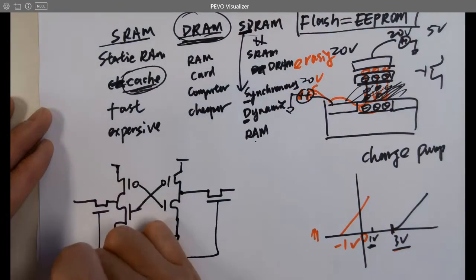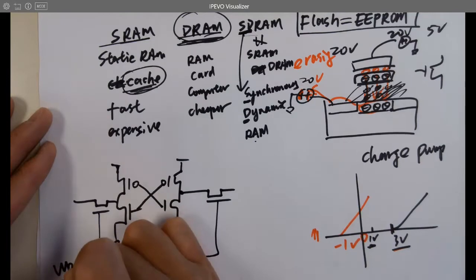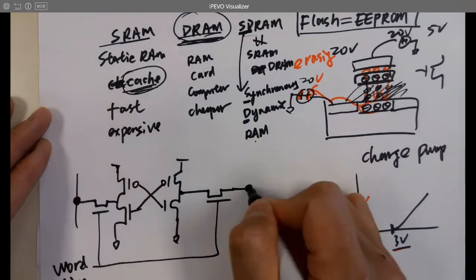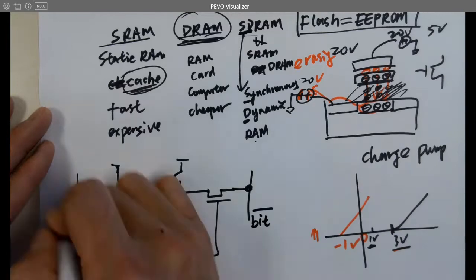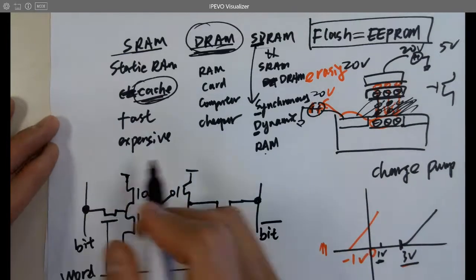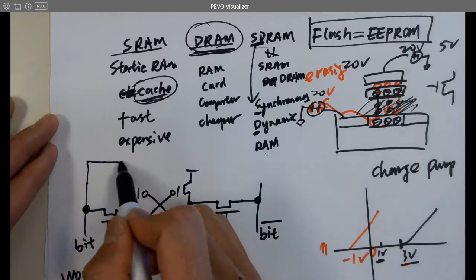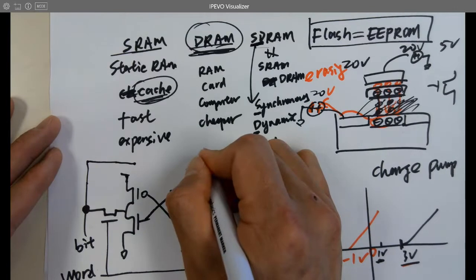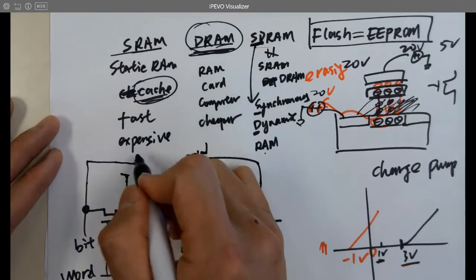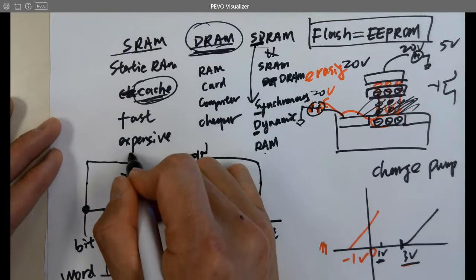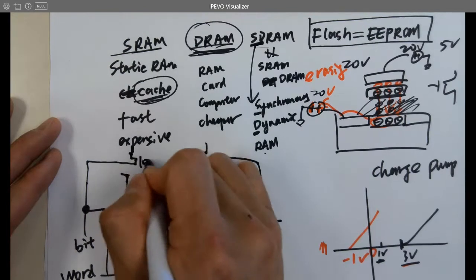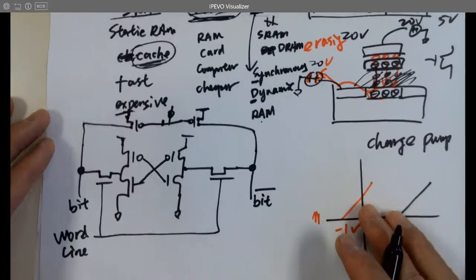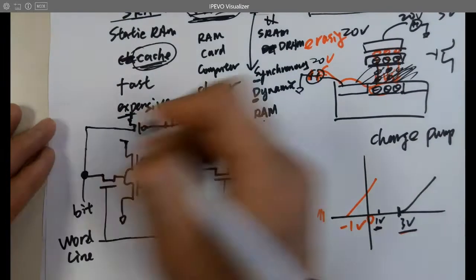Here's the word line. It's just selection from the decoder. And these are the bit lines. So this is the bit bar. This is bit. That's when you read and write, that's a bit. And then here you have to use a circuit to make a floating VDD. So these are VDDs, and here's a clock. How that works, you have to make a floating VDD here first.